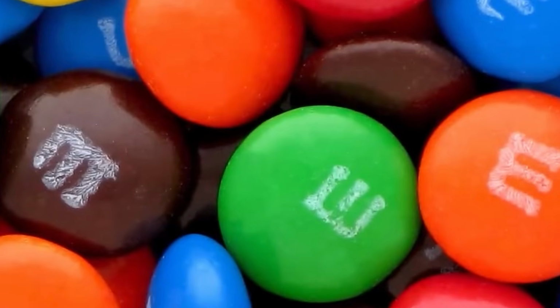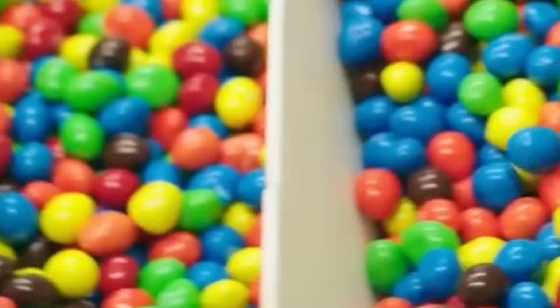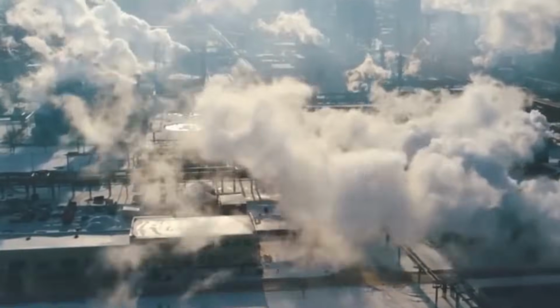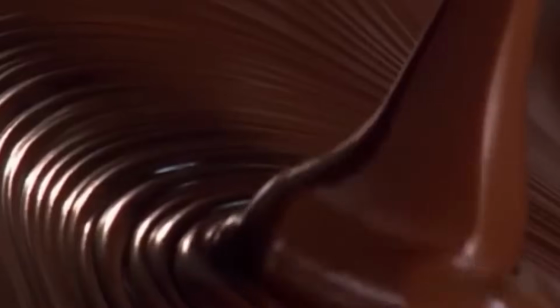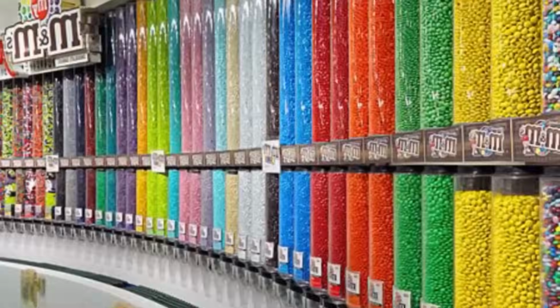After cutting, the caramel centers are conveyed to a pre-coating drum where they are tumbled with a fine mist of modified starch or food-grade wax. This stage prevents sticking and prepares the surface for chocolate adhesion. The pre-coated caramel pieces are temporarily stored in stainless steel bins under humidity-controlled conditions with less than 40% RH before being transferred to the chocolate panning units.